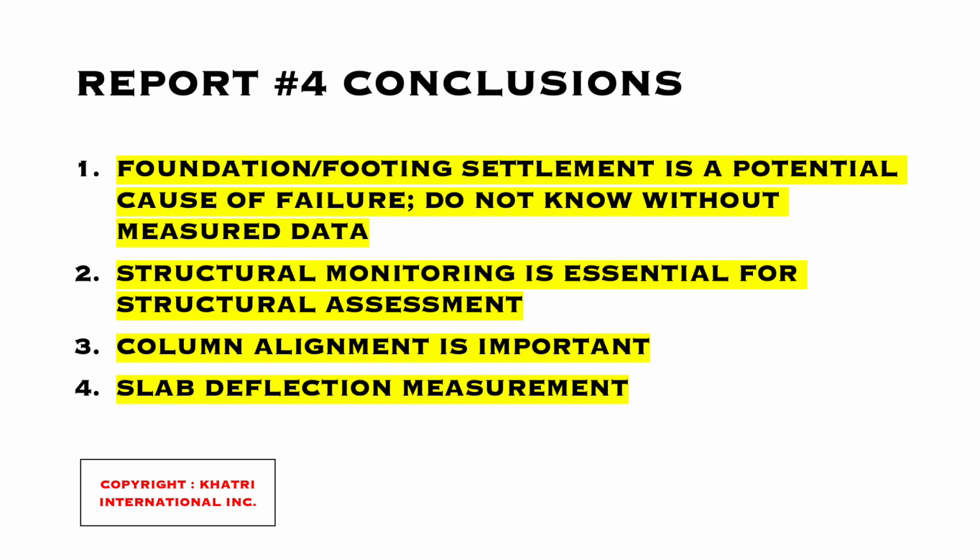For report number 4, my conclusions, which follow through with reports number 2 and 3: foundation and footing settlement is a potential cause of failure. We do not know for Champlain without any measured data. Structural monitoring is essential. We've got to monitor our buildings. We've got to look at the column alignment.